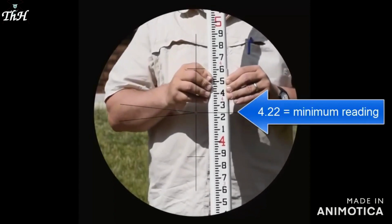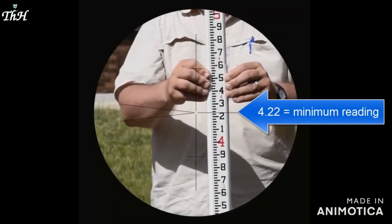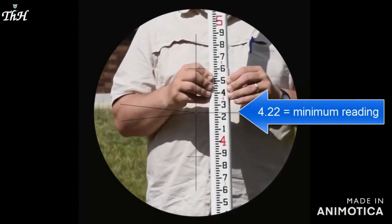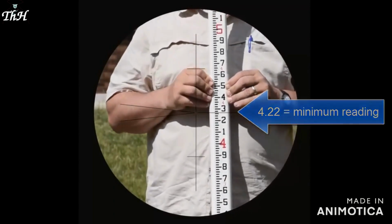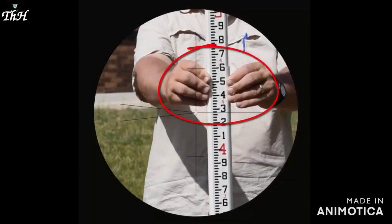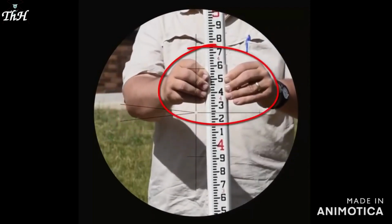Use your peripheral vision to search out visual clues to help you keep the rod plumb, left and right, as you rock it smoothly forward and back. Do your survey partner a favor. Grip the rod by its sides to prevent your fingers from obstructing the readings. These methods are designed to minimize errors, but it is impossible to completely eliminate measurement errors.